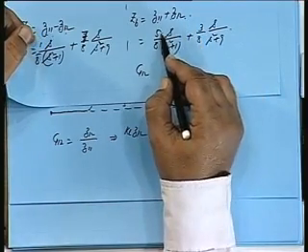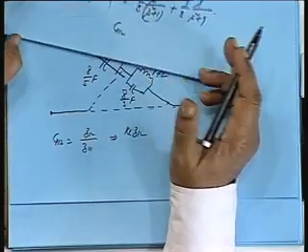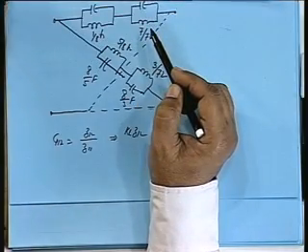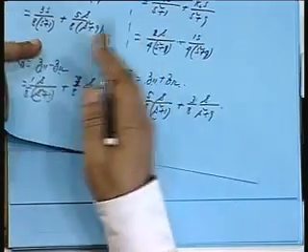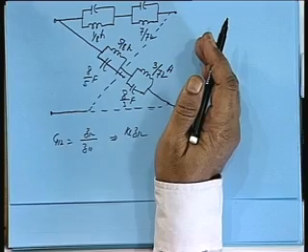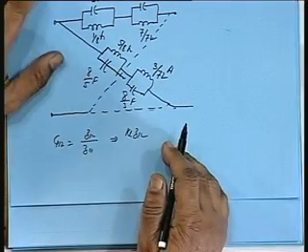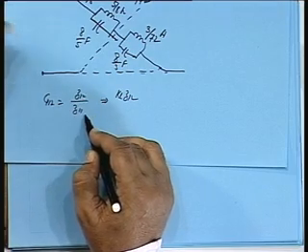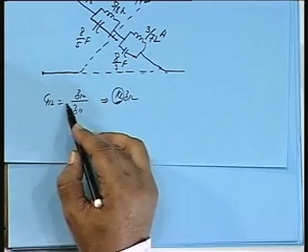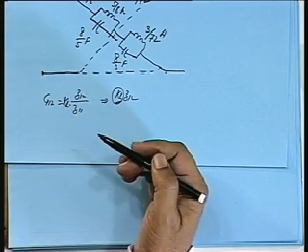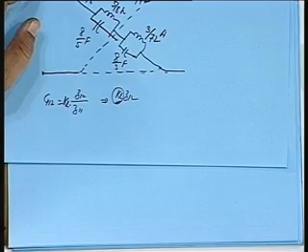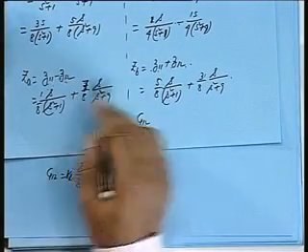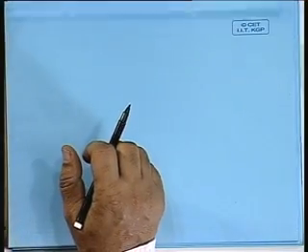So all these will be multiplied by a factor KL, and we can adjust the value of KL such that every time, whether it is Z11 minus Z12 or Z11 plus Z12, all of them will be positive real, because there may be a negative sign here. So sometimes we will be adding, sometimes we will be subtracting, so some of them may turn out to be negative if we do not have a factor KL. So KL is an adjustable parameter. So G12 is Z12 by Z11, and we can adjust KL. So we will write KL as a multiplying factor. So for this problem, what is the maximum value of KL so that we can realize a lattice network? Okay. So we will take up these values now.